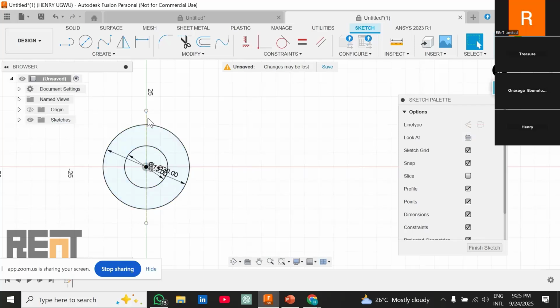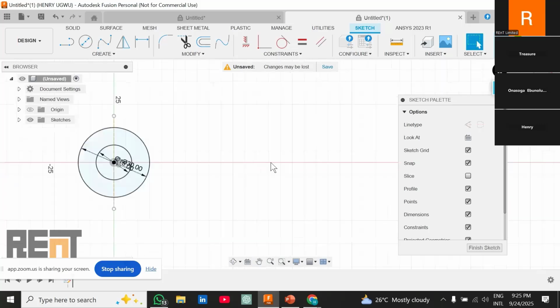You know what construction line means for engineering students. When you are doing your engineering drawing, construction lines are used to reference design. They are not imported into the final model of that design. Okay, so I'm going to create those 4 lines first. I will go back to the Line command, activate it, and draw 4